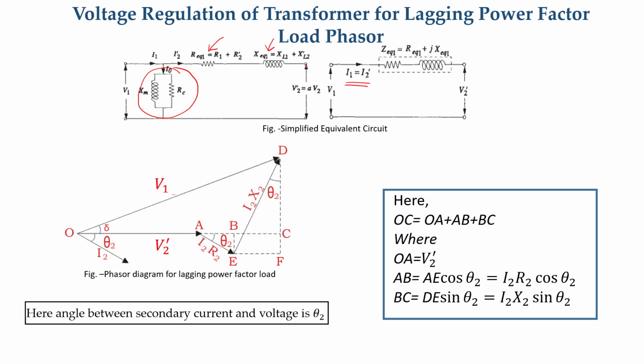In that case, you can assume an ideal transformer at the end, because all the actual practical parameters are represented here. So at the end you can assume the ideal transformer and then V2. Where A is the turns ratio, you will get AV2 on one side and simply V2 on the other side, so V1 to V2. Similarly, if the shunt branch is neglected, you can simply see this series branch and the relationship between V2 dash and V1. The phasor diagram of that is given here.